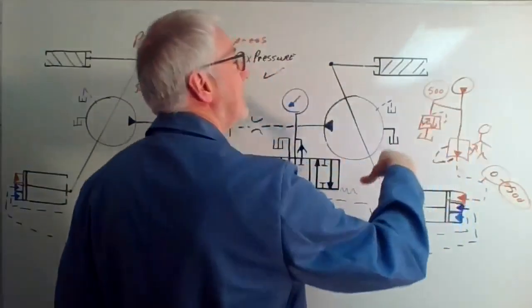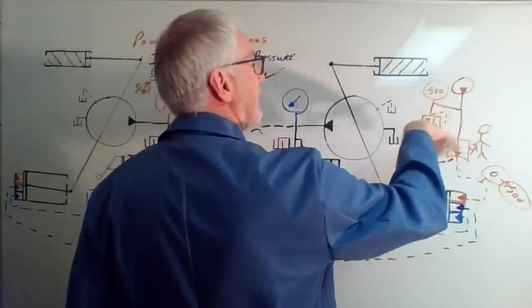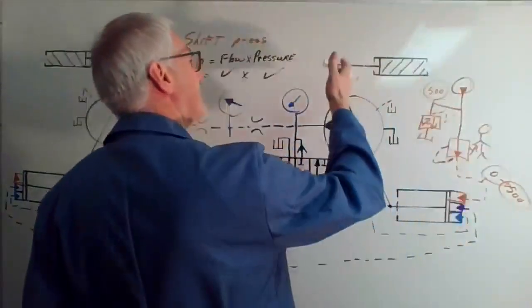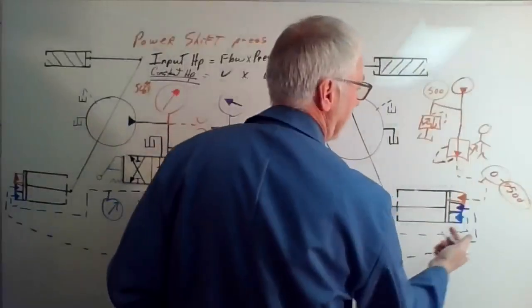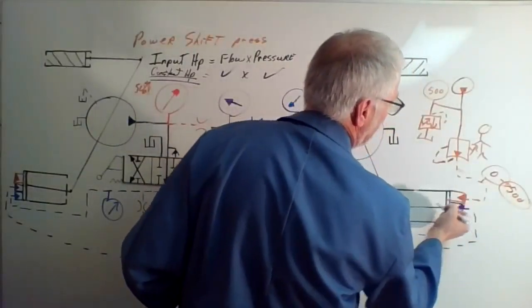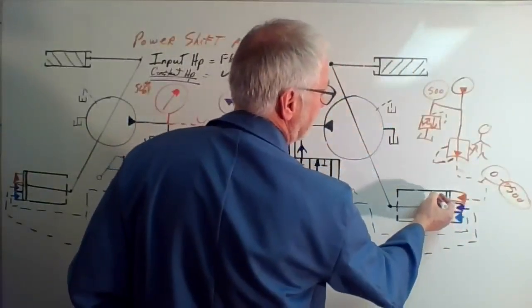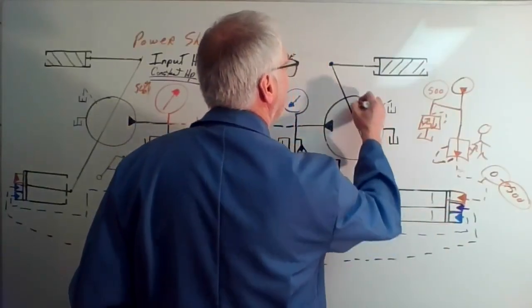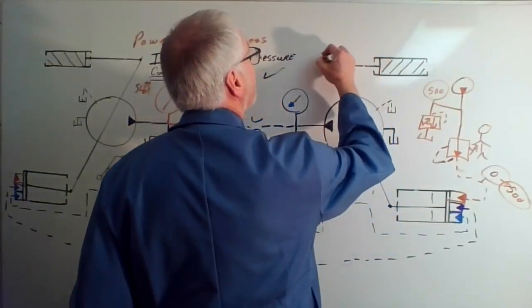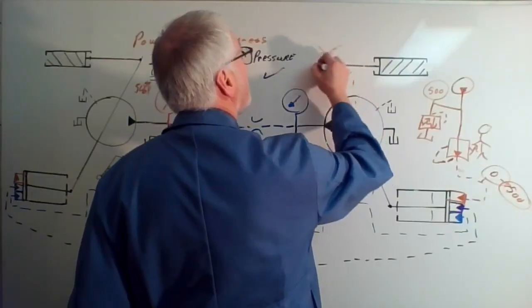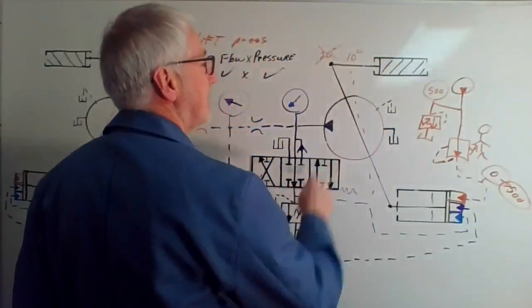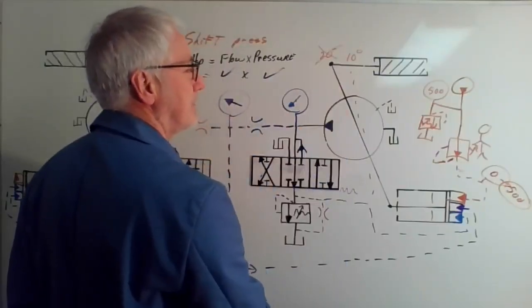So we steal oil out of the pilot system, which is the control side of it, and we control whatever that constant horsepower is. If I throw some pressure at it, that would try and de-stroke this. And now instead of 20 degrees max, I can only get maybe 10 degrees maximum on this particular pump.